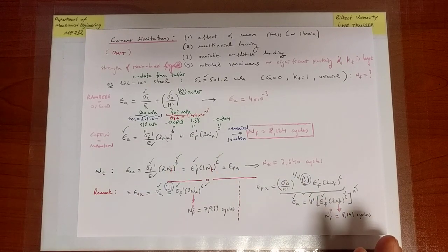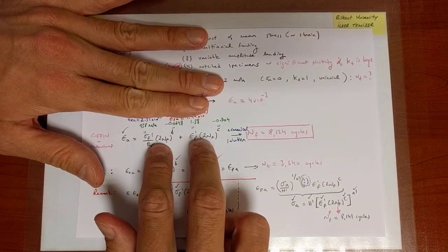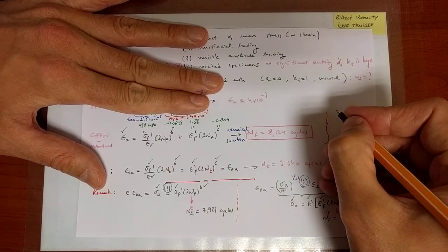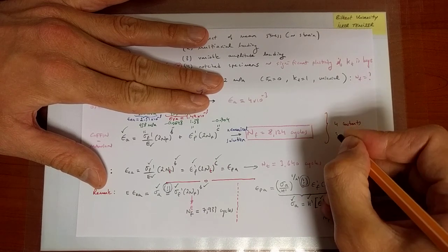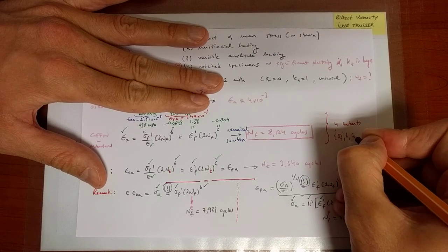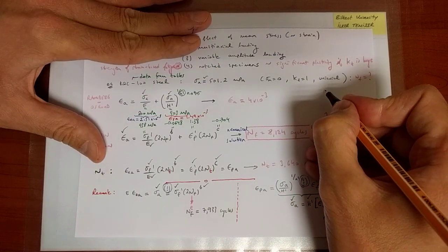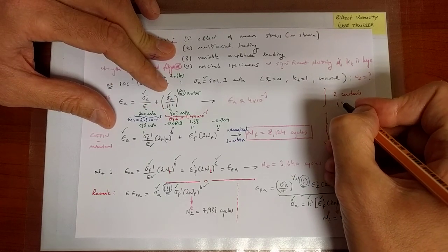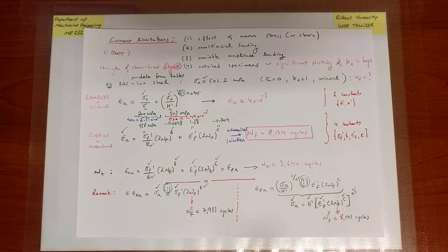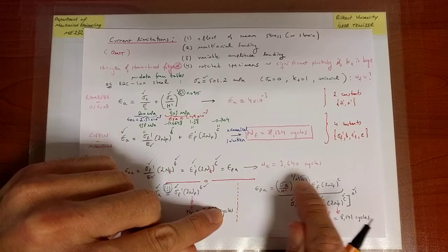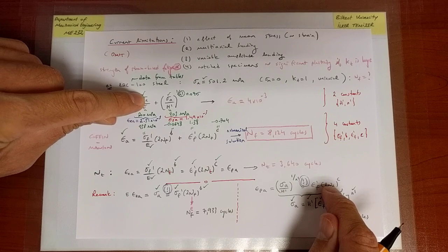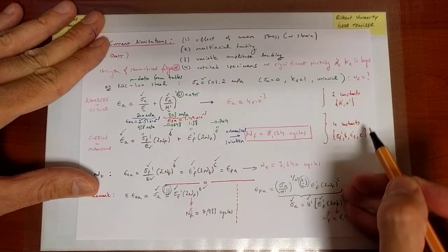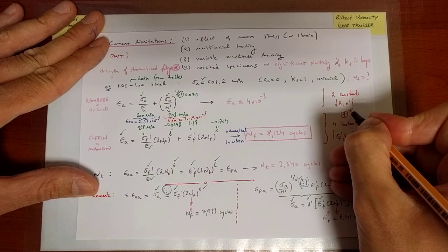And the reason is because when you look here, you see actually here 4 constants, right? So let's make a note of that with red. So here we have 4 constants, which are sigma f prime, b, epsilon prime f, and c. Here, in this model, we have 2 constants. But really, additionally, we need to say that this actually is equal to that. And let's say this is equal to that. That actually places 2 additional constraints such that I don't have overall 6 constants. Okay, so let's put an exclamation mark here as well.